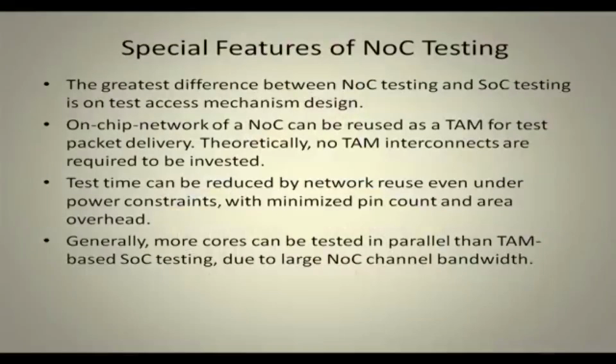So, in SOC we solved that problem by having a dedicated test bus or test architecture embedded into it, and then from this input port, from the ATE, we are feeding the test patterns to the test architecture, and the responses are obtained. So, that way it was solved by having some additional test architecture embedded into the SOC. On the other hand, in this one,